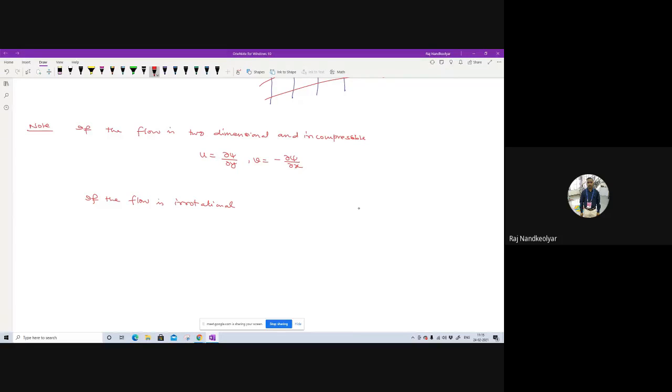जो स्ट्रीम फंक्शन तुमने लिया है वो ऐसा चूज किया है कि u इज डेल साई अपॉन डेल y एंड v इज माइनस डेल साई अपॉन डेल x, and you are telling that the flow is two dimensional and it is irrotational now. So obviously it has to be, अगर रोटेशनल होता तो किस एक्सिस के अबाउट होता, जेड एक्सिस, जेड एक्सिस के अबाउट होता ना. तो इफ द फ्लो इज irrotational it means what, angular velocity along z axis is 0. Is that fine? Omega z equal to 0.